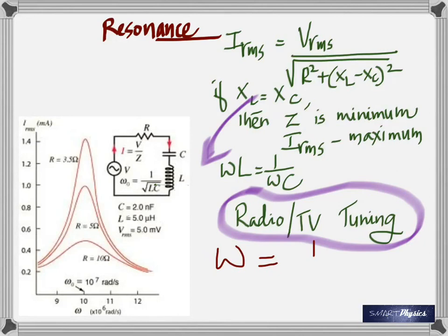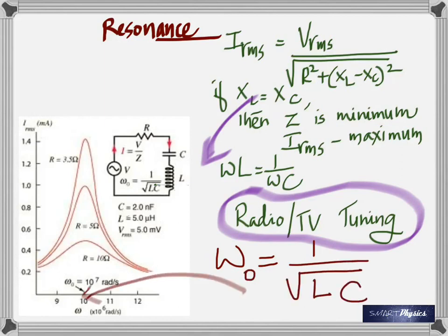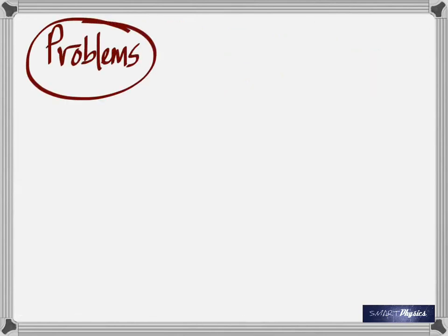In fact, there are 2 terms that you've got to read about. It's called the quality factor and the sharpness of resonance. Lack of time. So read those 2. Sharpness of resonance and the quality factor depends on the value of resistance. To summarize, the frequency at which resonance takes place does not depend on the resistance. You heard that, right? But the sharpness of resonance depends on what? On the value of the resistance. Okay, again, finally summarizing, that is the resonant frequency. That is the end of this magnificent chapter. Good luck.